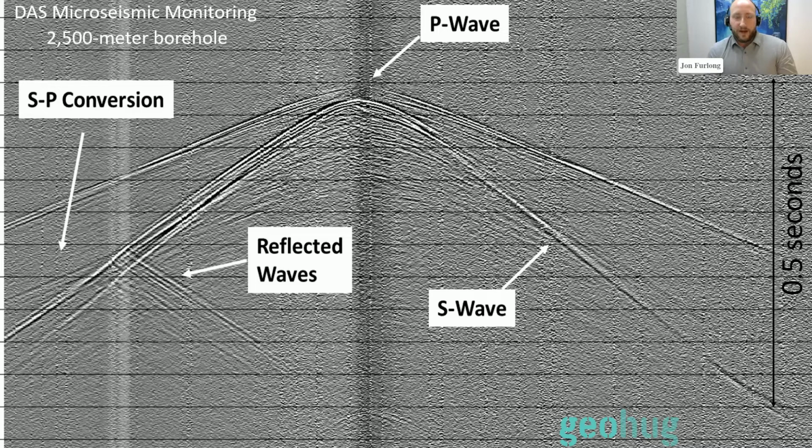And for those of us who've processed any amount of microseismic events, we know how susceptible we are when doing microseismic event locations to the velocity model uncertainty, especially in mines when we have really heterogeneous velocity models. So we oftentimes just have to go with a static velocity because they're so dynamic and changing that we can't always be updating them. So what we can agree on here is that with more sample points, you're able to reduce your location errors by using all of that aperture in your location.